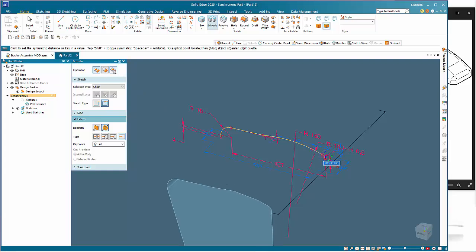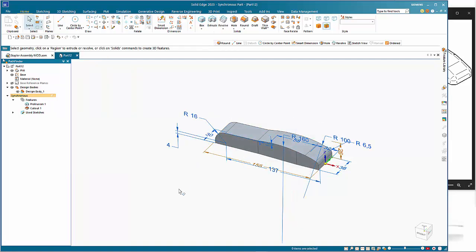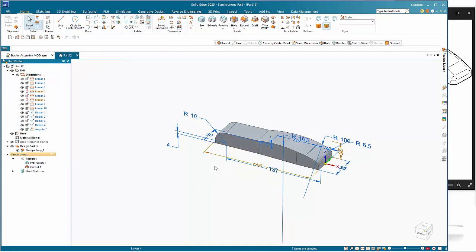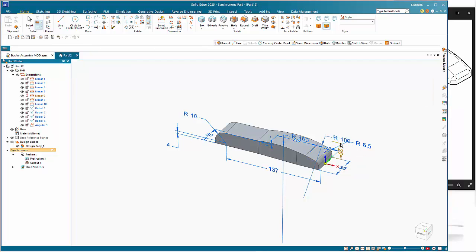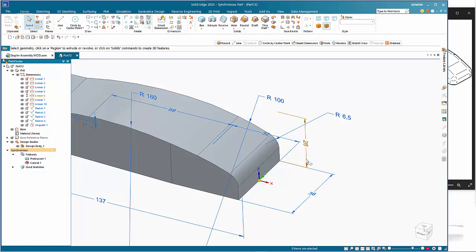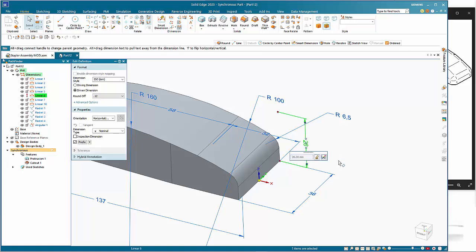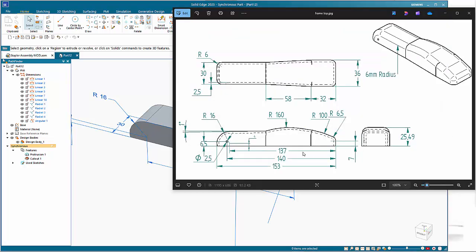And as you can see, it's trying to create a solid, so we need to do a cut, and that just then cuts away that top edge, as you can see in there, and dimensions drop out. This one has lost the edge that it's gone to, so I'll get rid of that one, and this one here. So that gives me my overall profile.